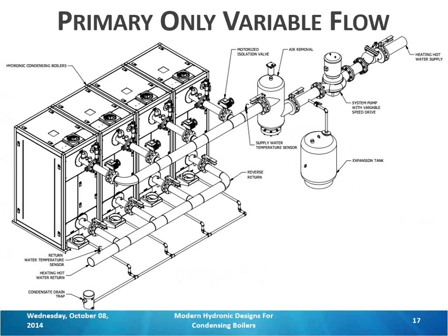So why do we care? Well, for one, if you're sending hot water through a boiler that's not actually firing, and you have a tall chimney going up inside that building, what does hot air want to do? And what are you going to get through that boiler? Draft, right? So you're actually going to be pulling the heat out of your system, just sending it out into the atmosphere. And any boilers that are running, now they have to go up a little bit in their burners to make up for that temperature loss. And depending, it can be pretty minor, but you are losing heat, and it's easily avoided.